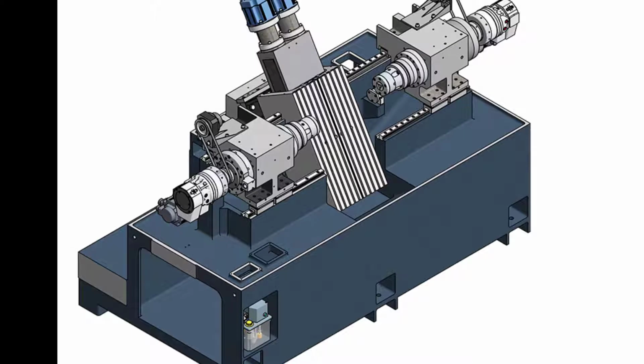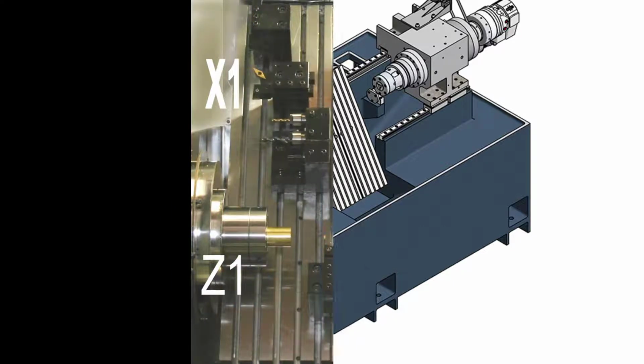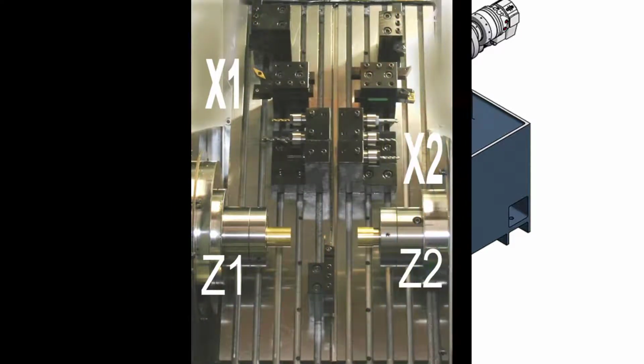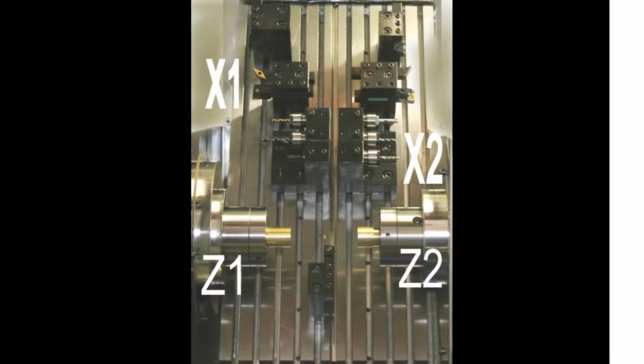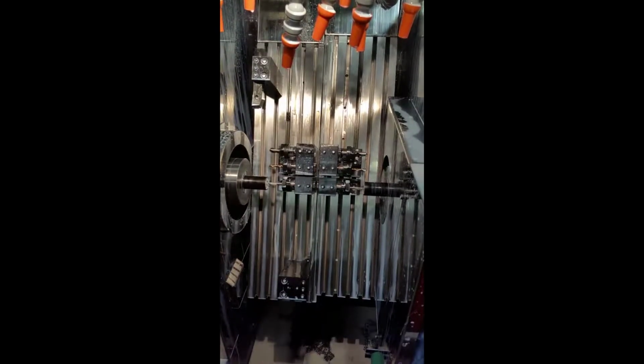This machine is two machines in one. We will use the main spindle, also known as spindle 1, to introduce the material and finish the front of the part. Then we pass the part to the sub-spindle, known as machine 2, to finish the back of the part and eject it from the machine.